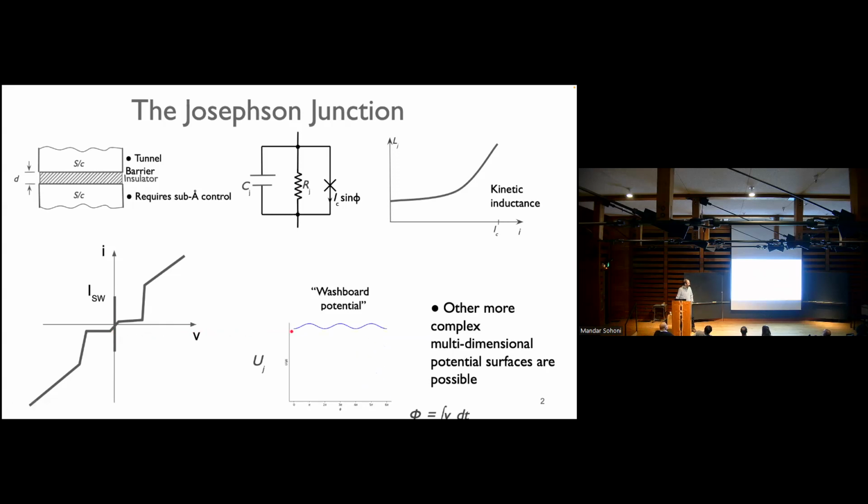You can also visualize it as a physical system. It's often thought of as containing a pseudopotential related to the energy in the device. The x-axis here is the phase, which is basically the flux. It's the integral of the voltage on the device. And the Josephson junction canonically makes this kind of washboard potential shape. You can change that shape with the current that goes through it. So you have a knob with which you can turn this device.